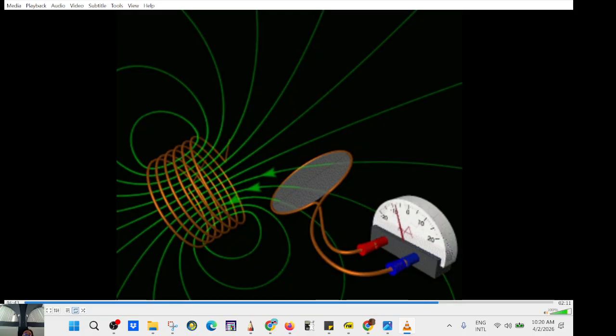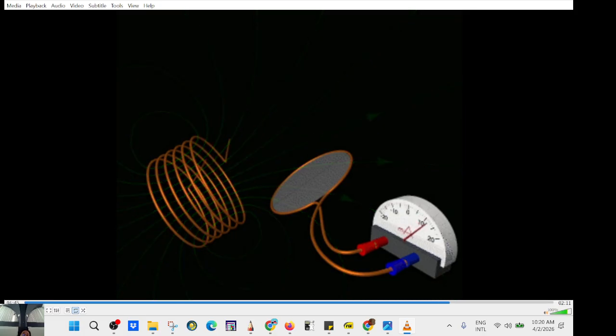Oh, that's another example. So here you have an electromagnet and you turn it on and off, right? So it's connected to a power supply. You turn on the power supply, turn off. So the magnetic field will expand, collapse, expand, collapse. So the number of field lines poking through this invisible membrane is changing with time. So you are inducing voltage, you are inducing current, right?